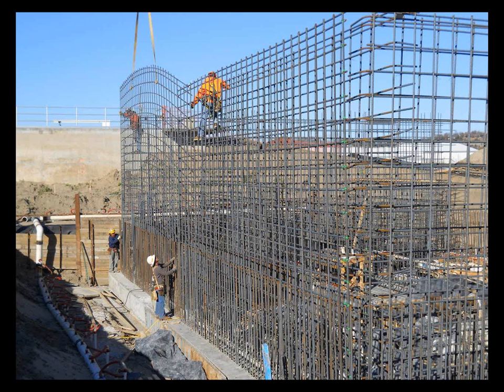Here you see the footings have already been poured. The white pipe you see to the bottom left corner of the slide and all the way around is an underground well system. We had to pump dry sand points down in the water because we are, again, close to the river, and keep groundwater pumped out while the construction was going on.